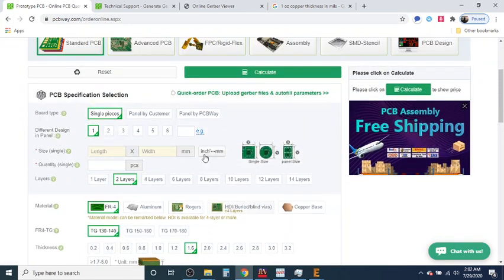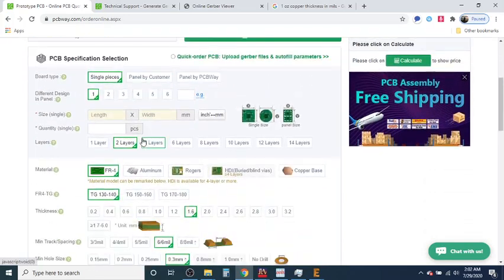I don't understand why, but there is one thing that they do not include: you can't use an aluminum substrate, which would actually be better for a low noise amplifier, because it should help your signal quality and give low losses in the circuit.